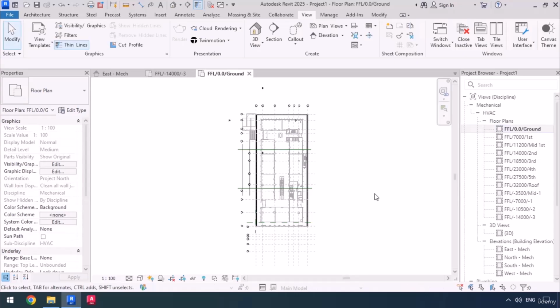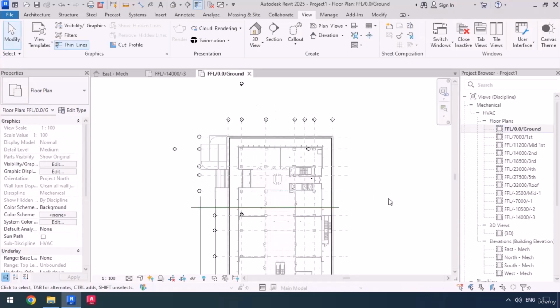Now you see when it comes to the mechanicals, we have separate plans. As in, for example, we have one sheet for the sanitary, then there's also another sheet for the domestic pipes, then there's another plan for the ventilation ducts, the hydronic or heating and cooling pipes, as well as the discharge ducts if there's any. Basically, each one of these categories go into a separate plan. So based on the categories that I've just named, we would have 5 plans. Now in some other projects, we might have different plans for different floors, as in there might be some more disciplines based on the project's function.